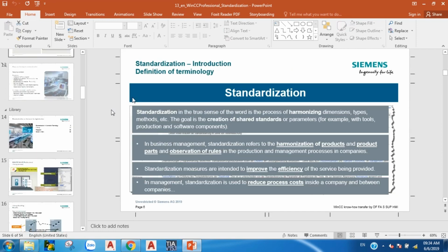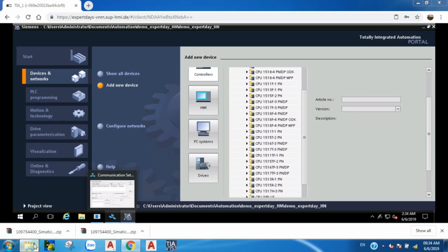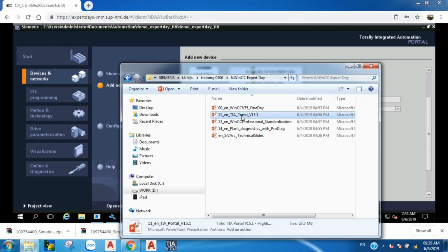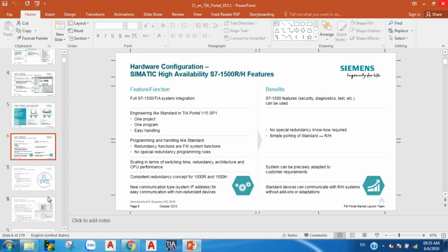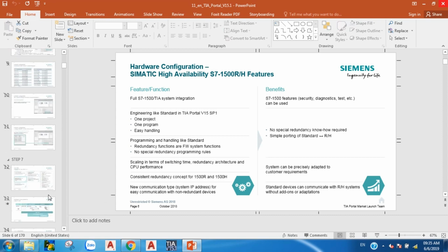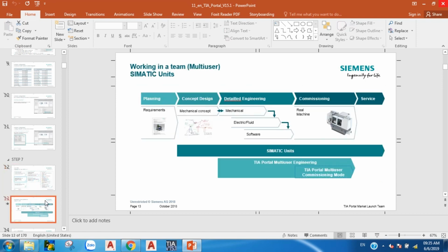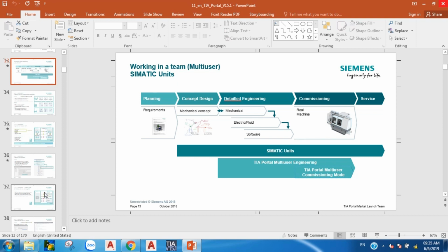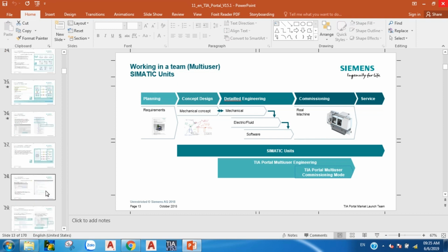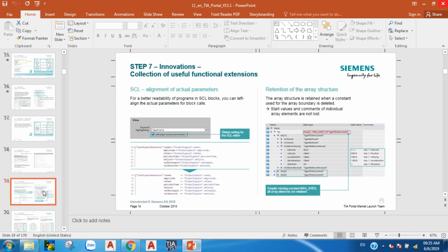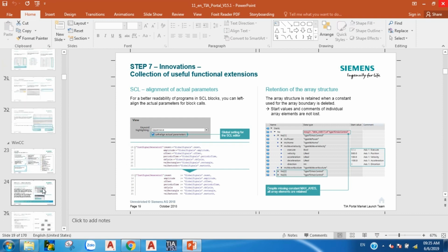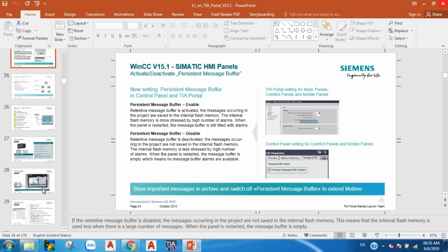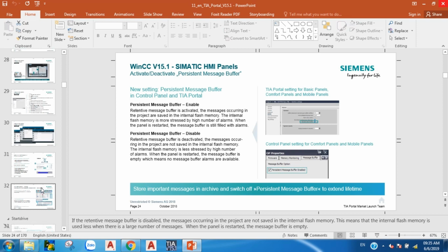What we did include now for WinCC Advanced, this was just possible for WinCC Professional before. If you have a failure in any operand or any interlock in the PLC program, you can now also jump from the runtime into this specific faulty function block in the TIA Portal engineering, and you can also set the view in the TIA Portal engineering software to read only, so no changes can be done in the engineering there.